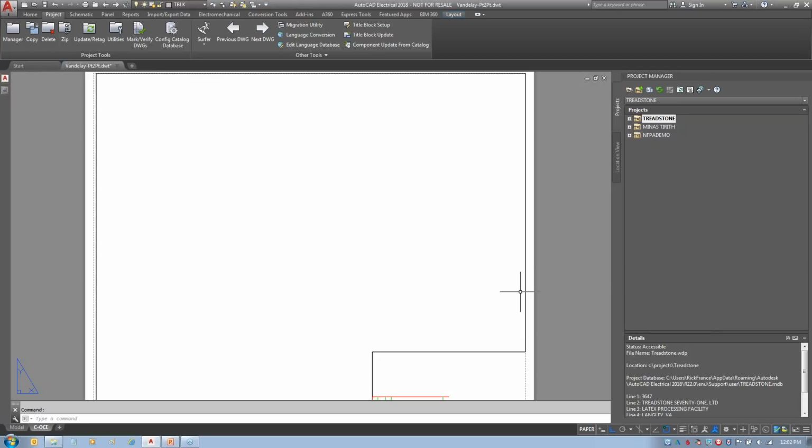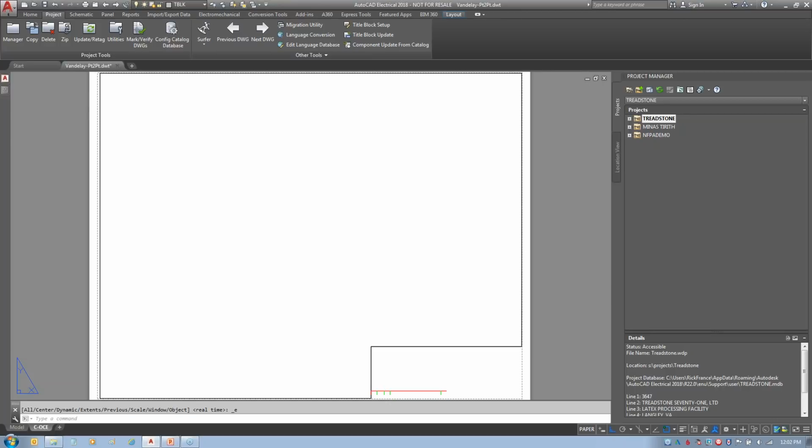It also does not have the title block in it. It is a little further down the road than a regular generic AutoCAD template, because I've already got the viewport in it, looking into paper space, and it's ready for my title block to be inserted. So we're going to start with that.